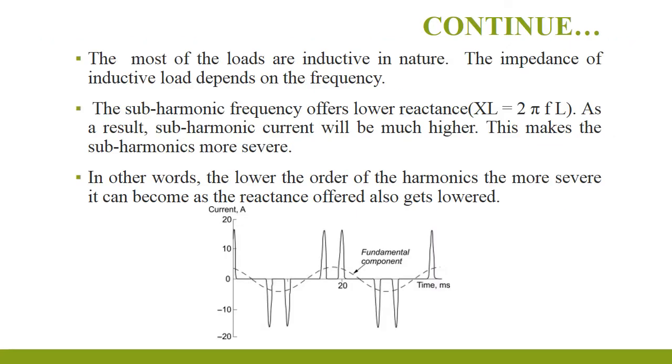Most of the loads are inductive in nature. The impedance of an inductive load depends on the frequency. The subharmonic frequency offers low reactance, XL equals 2 pi f L. As a result, the subharmonic current will be much higher. This makes the subharmonics more severe. In other words, the lower the order of the harmonics, the more severe it can become, as the reactance offered also gets lower, as we can see in the picture.